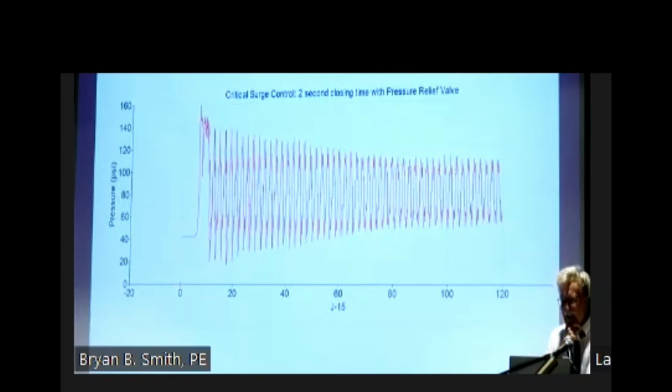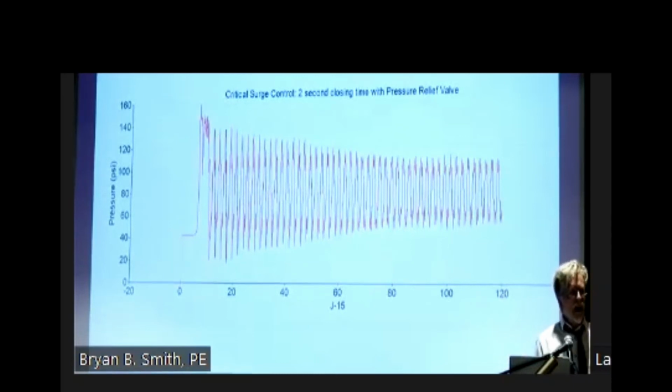Wait, a second later, the high pressure wave comes back. So this is where I'm illustrating the pressure transient as it's going back and forth in this poor relief valve. Open, close, open, close, open, close. So the reaction time of your relief valve is critical in this type of application. Yes, you can size your relief valve. And in many cases in large diameter piping systems, like when I was doing a crude oil pipeline, I needed my valve to open up in a fraction of a second and then close slowly, so I didn't get this pressure transient going on within the system.